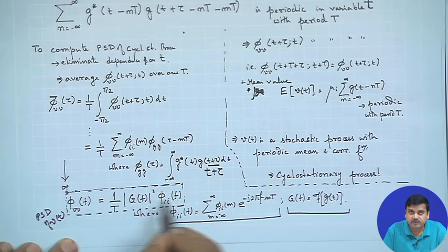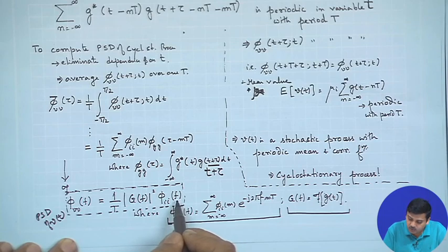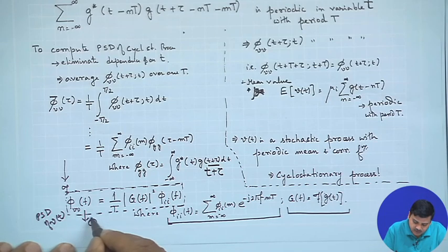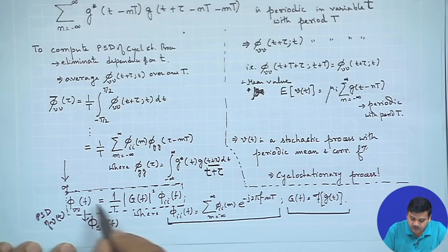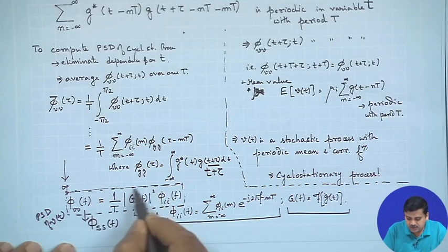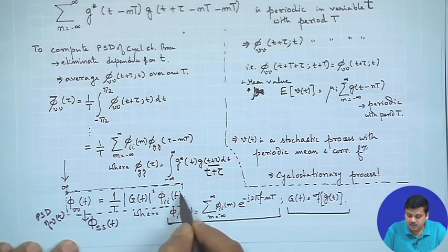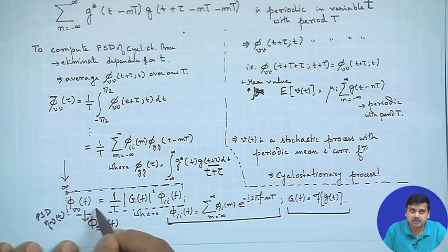So, we have two different parts to it. If we have to control the characteristics of this, because this influences the PSD, from this you could go to phi SS of f through the relationships which we had shown before. You can clearly see that you have a choice to work with the pulse shape, which would result in certain spectral characteristics, as well as a choice to work with the information bearing signal, to try to get the desired characteristics.